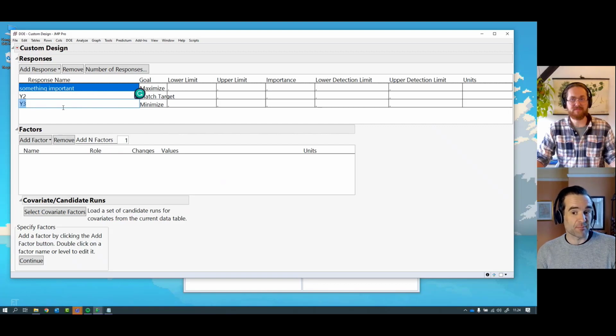I can remember an example in industry where I was helping out doing a designed experiment on a process, and the results of the whole thing came back. We'd spent a couple of weeks doing the experiment, and there were 3 repeat runs within the experiment, and the response was on a percentage scale. And the 3 repeat runs, same factor settings, the range of answers we got were between like 20% and 80%. So it was just all over the place. And it just turns out we couldn't measure the outcome that we cared about repeatably, and we didn't really have control of the process.